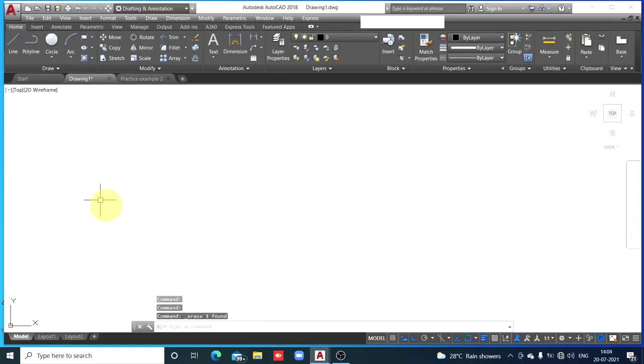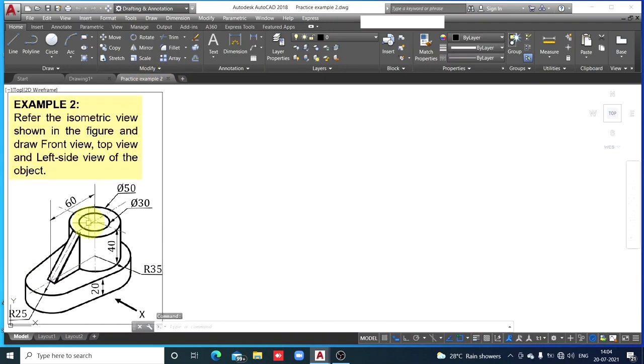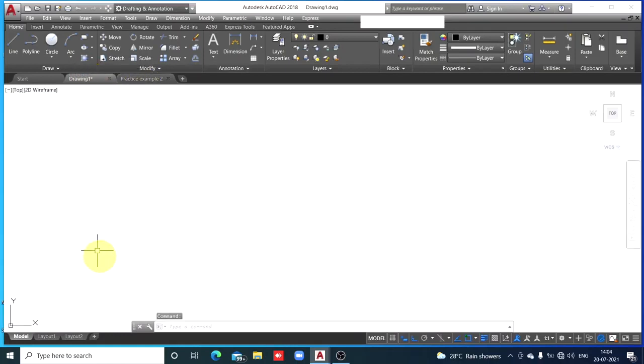Okay. What are the dimensions of the object we are discussing right now? Length 120, height 60 and width 70. So the space required for our drawing is approximately 300 millimeters vertical, 400 millimeters horizontal. That much space is enough, we may say. So we'll set the limit for our page in this manner.